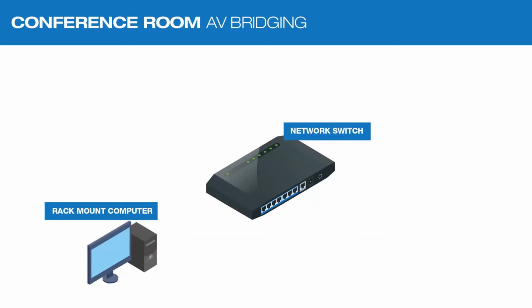There is normally a network point or network system in the room or in the building, and we'll work on this. Q-SYS makes use of gigabit networks. Standard gigabit networks is fine for Q-SYS. So you just need PoE ports for some of the devices.